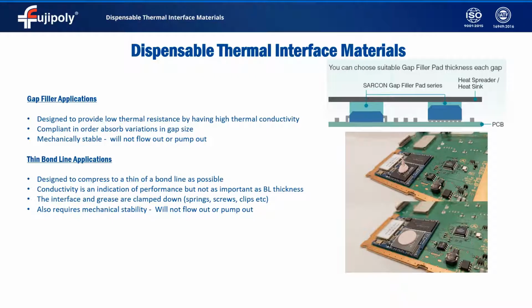PCB deflection specifications and fastening limitations, right? The number of places where you can place your fasteners, those often pose design problems, and a lot of times you'll have to turn to a dispensable soft material to solve that.